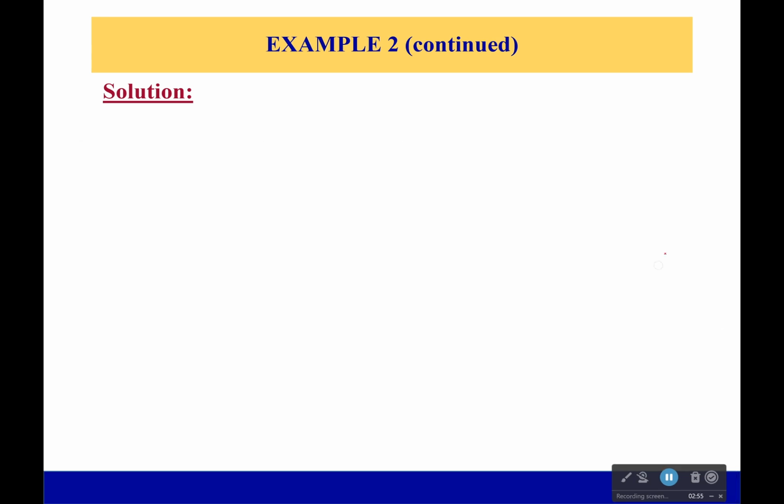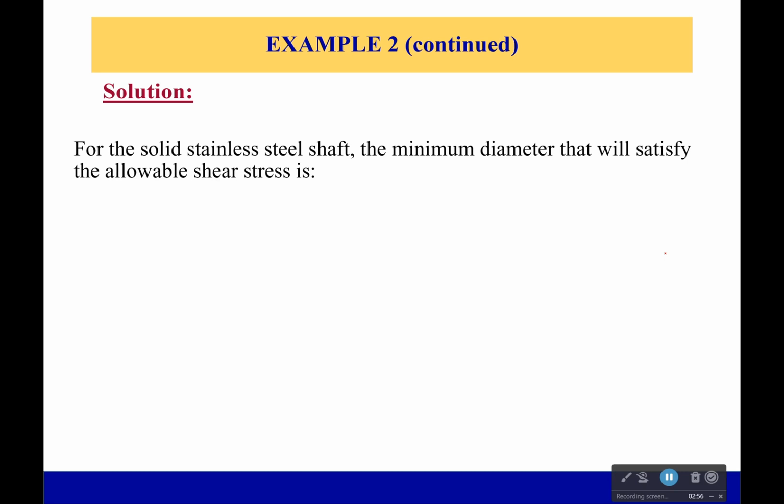Okay, now with that, we can finally start to calculate the minimum diameter that's going to satisfy our allowable shear stress. When we plug that in, we get our diameter has to be more than or equal to 0.831 inches. Just be very careful because this is pound inch right here. So we had to switch from KSI to PSI right there. It's a little bit difficult with those prefixes when you're in English units rather than in our metric units.